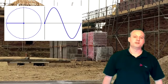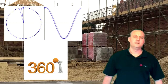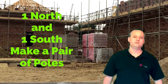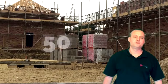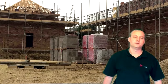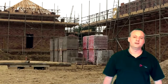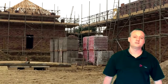We looked at how we could produce an AC waveform by rotating a conductor 360 degrees in a magnetic field placed between a north and south pole. A pair of poles, so the machine would have a north and south pole. We said the machine had a pair of poles, and if we rotated it 50 times in 1 second, we would produce a frequency of 50 hertz. We then looked at if we added a second pair of poles, so in other words another north and south, making the machine have 2 pairs of poles, so 2 souths and 2 norths, and we rotate the same coil of wire through the magnetic field, we had to rotate it half as fast in order to produce a 50 hertz cycle.